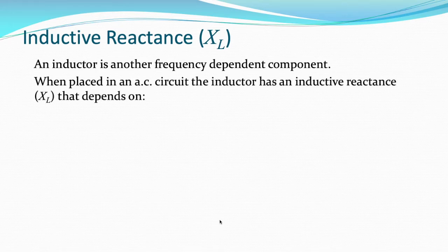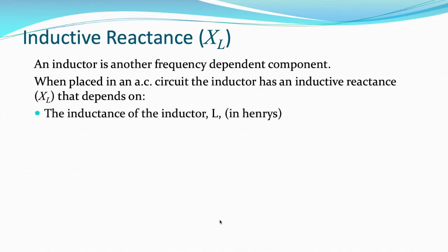When you place it in an AC circuit, the inductor has an inductive reactance that depends on the size of the inductor, or should I say the inductance of the inductor, which is measured in henries, and the frequency of the AC supply, which is measured in hertz.